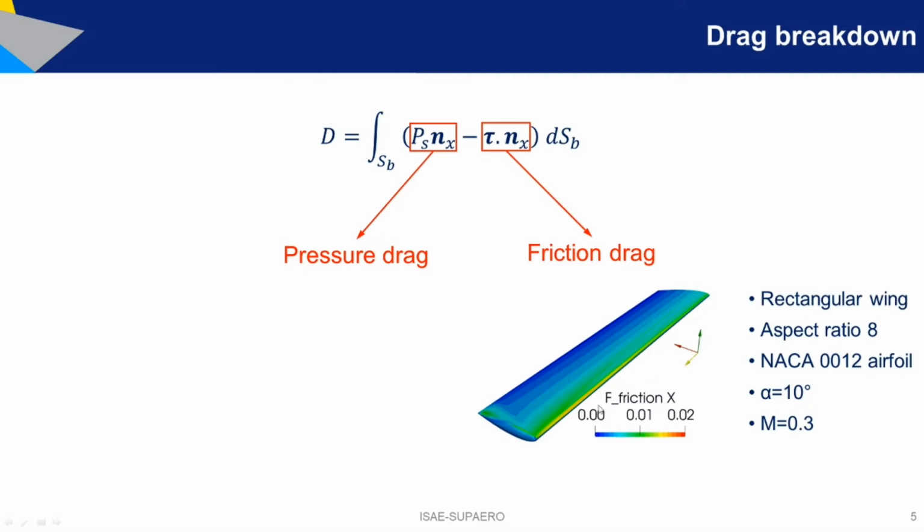So basically the friction forces are related to the local velocity around the surface. In order to reduce the friction drag, you have to deform the geometry in order to reduce the local high velocity. And that's the basis of the laminar airfoils. Laminar airfoils are geometries that reduce the over-velocity nearby the leading edge and provide a smoother velocity increase all along the chord, and this reduces the friction drag.